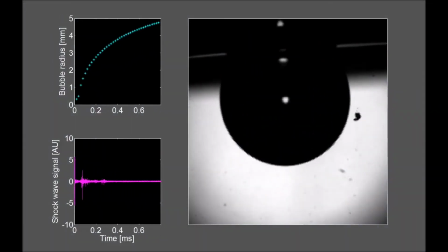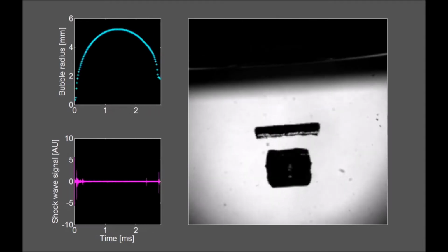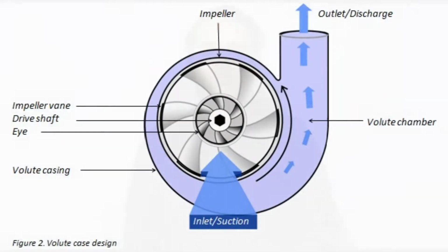When vapor bubbles collapse inside the pump, the liquid strikes the metal parts at the speed of sound. The noise generated from these collisions of gas bubbles into the metal parts of the pump sounds like pumping marbles and stones. Cavitation can be a serious obstacle to smooth operation of a centrifugal pump. Therefore, it is important to understand different pump cavitation causes in order to prevent pump cavitation.